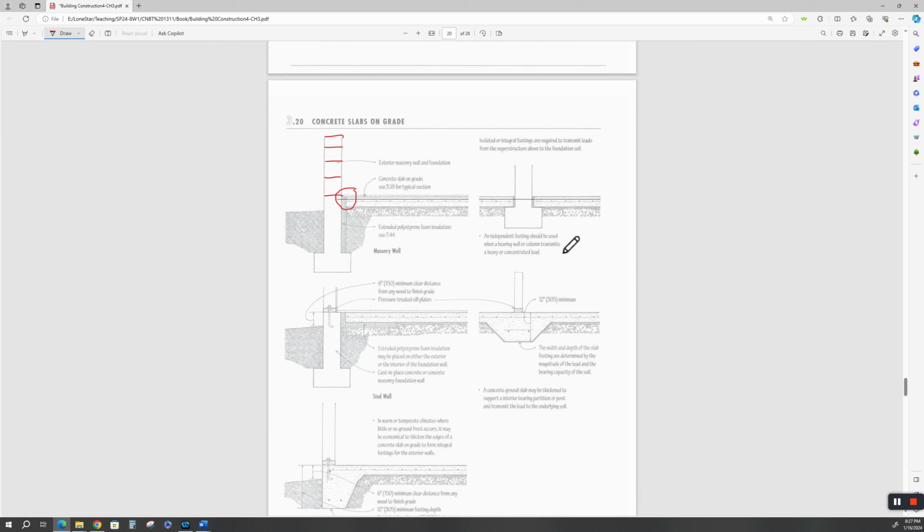This would be an example of an interior where you have either a load-bearing wall or a footing. Well, you got a footing, but this could either be a masonry load-bearing wall, or it could be a footing coming up, and then you have an interior wall, whether it's wood, steel, or masonry up from there. I would not extend my wall below this line. If you're going to do this, it needs to be in there, that way your wall material is not below the grade for termites and stuff like that to wick up into your house or your structure.